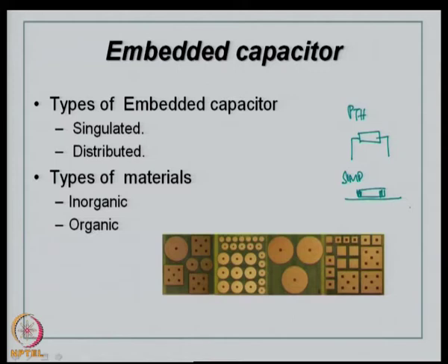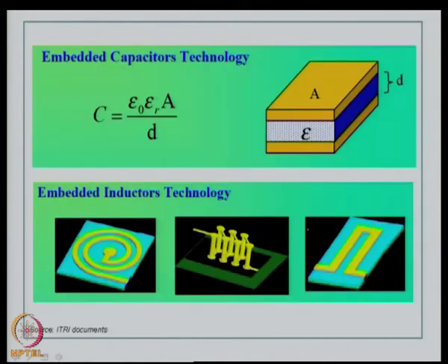So, how do we go about working with embedded capacitors when there is already a challenge in terms of availability of small formats of SMD devices, especially 01005, or 0201, which is already a well known standard?